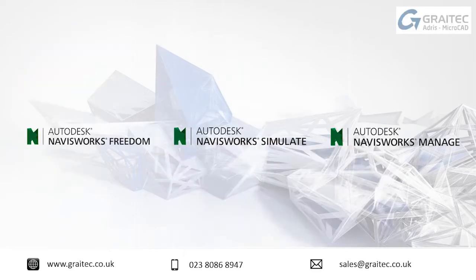There are 3 versions of Navisworks available to you. The first one is Navisworks Freedom. This is purely and simply a viewer for what we call an NWD file format, and it's freely downloadable. So if you create any work within Simulate or Manage, we can send that to someone who can then review that information within Navisworks Freedom. The next level up from that, the one that comes with Building Design Suite Premium, and it comes with some of the other suites as well, is Navisworks Simulate. Now, Simulate will give you all the tools that Manage does except clash detection. So if you want to do clash detection, you need Navisworks Manage. And literally the only difference between Navisworks Manage and Navisworks Simulate is clash detection.